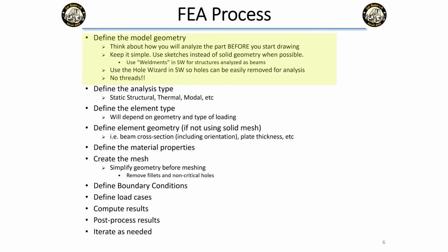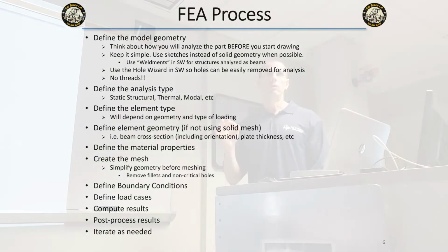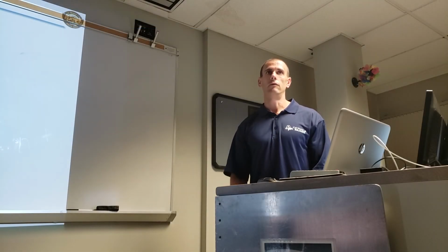And do not model threads. Never model threads. I mean, especially if you can do FEA. You should not have any threads in there. When you mesh it, it's going to try and mesh the threads, and it's not a good idea at all. So just do the pilot hole. That's going to be for the thread. I think there's an option in SolidWorks to show thread or not show thread.